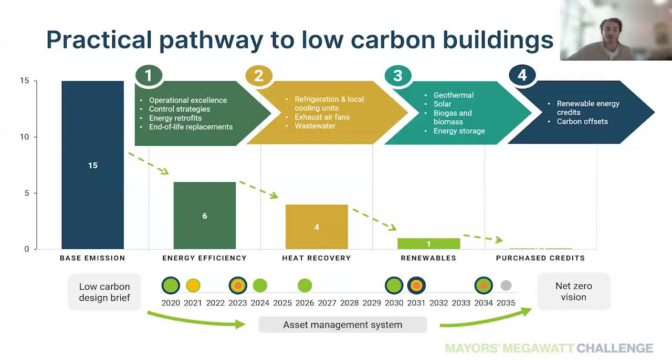And from there, you can determine with relative accuracy the impacts of different energy conservation measures and how much energy would actually be saved from various upgrades. Perhaps you have a furnace that you think is going to be consuming a lot of energy, but when you dig into it, you realize there are different units or baseboards serving that space as well that take the priority sequence. It's an internal space not getting much infiltration, a variety of considerations, but actually doing that analysis will give you a better understanding of what kind of savings you can expect.